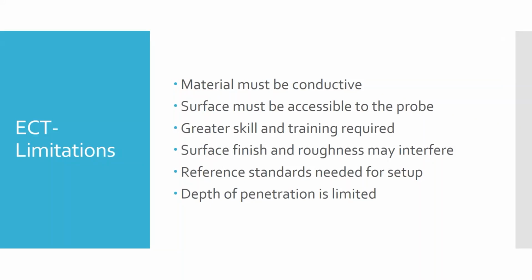And this one's different from some of our other methods, in that one thing we need here is a reference standard for setup. So you didn't need this for visual inspection, although you did use it with the combustion chamber. But you can perform visual inspection without having a second part to look at to compare it to. And you can perform magnetic particle inspection without having a reference standard or a second part to compare the one you're testing to. And you can perform liquid penetrant inspection, again, without having a second part or standard to compare it to.